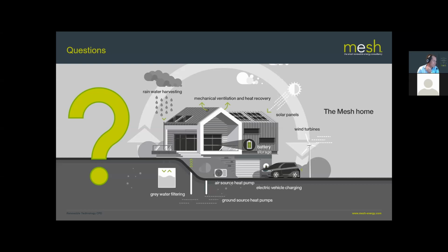What you do tend to do is put a larger hot water cylinder in with an air source heat pump than you would with a boiler, partly to offset that. And of course, you can also run an immersion heater in the cylinder from a solar PV system. You can use a product called a solar diverter, so that when you're generating electricity from your PV system which isn't being used on site, you can dump that electricity through the immersion heater to heat your hot water up to a higher temperature.